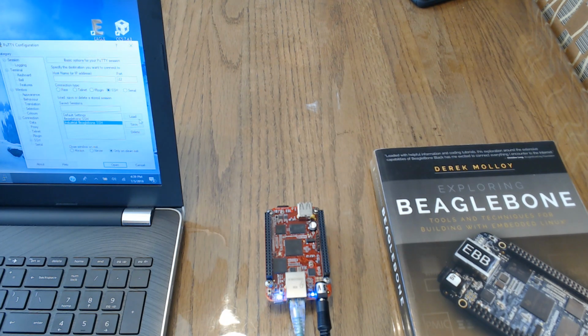So I just happen to know the IP address of this beaglebone, but you can also use the USB connection. If you're USB'd in, then it's going to be 192.168.7.2 because the beaglebone has its own IP network driver that it loads on your machine, so you can actually get IP connectivity to the device just plugging into the USB port. But then don't forget that it also is going to need that Ethernet connection, because you still need to be able to connect the thing to the internet to clone the Sandstar repository.